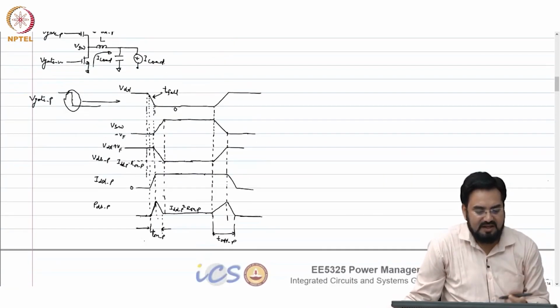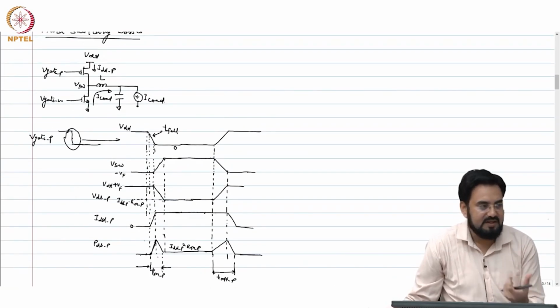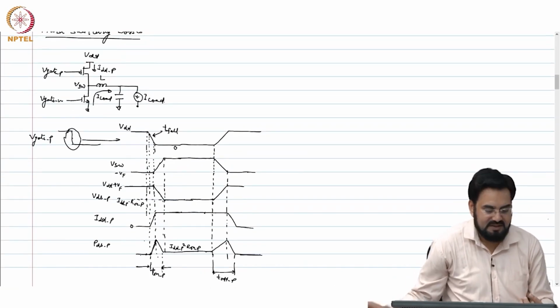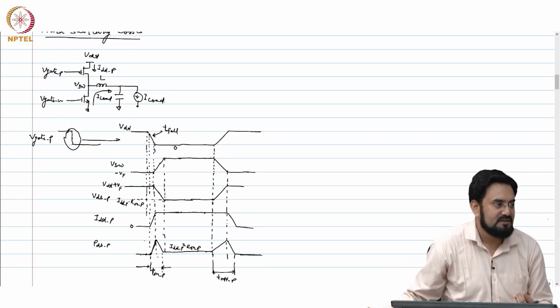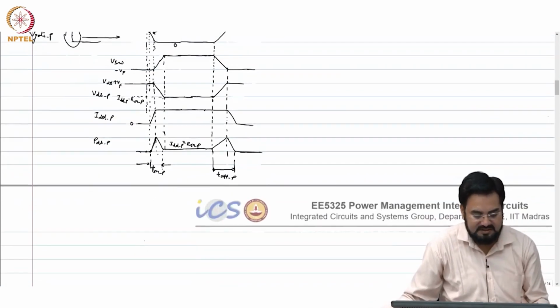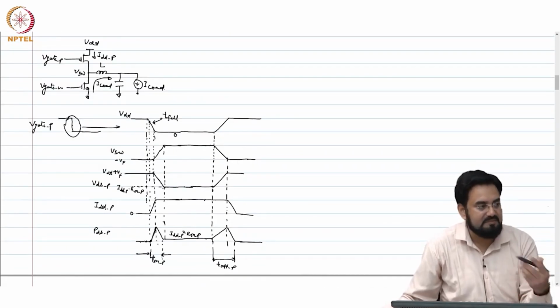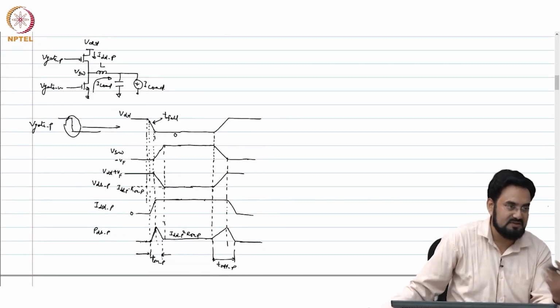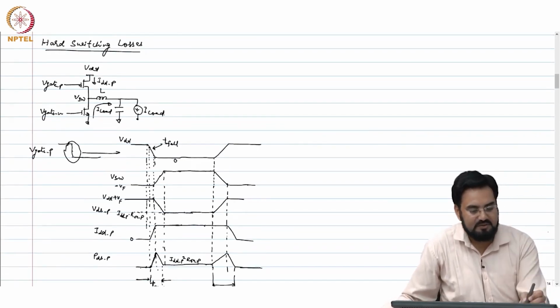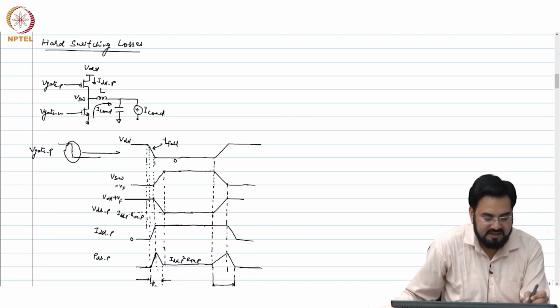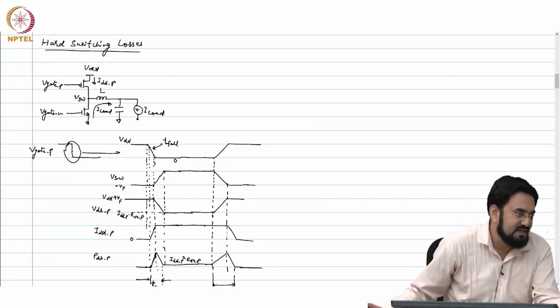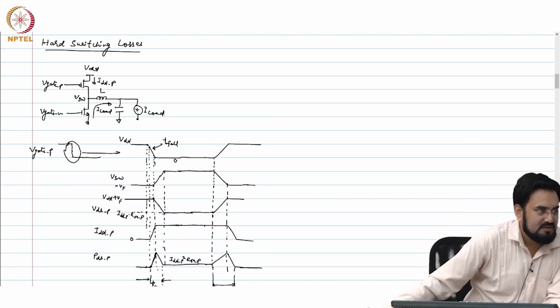correct, and you do not know at what point exactly your diode will turn on, but usually the VDS voltage is almost full when it turns on. So, the current starts, and there are some delays associated with the power FET, the intrinsic delays of power FET, which might be due to the parasitic cap at the gate, sorry, not the gate, at the drain, which is the intrinsic cap of your MOSFET, okay.